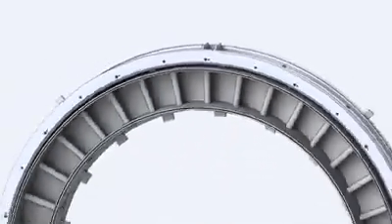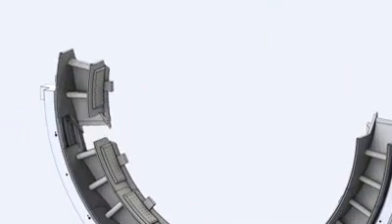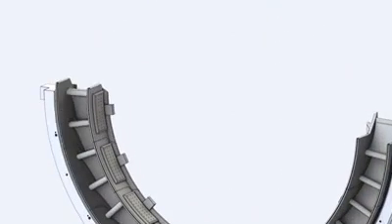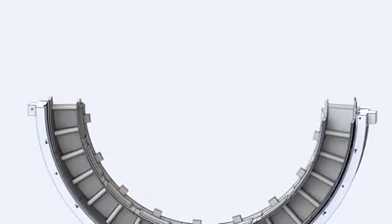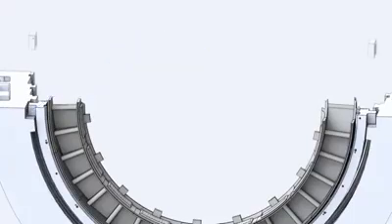The 18 segments are contained on a horizontally split retaining ring. The retaining ring is supported to the lower turbine shell by 2 lugs extruding from the lower retaining ring half and held in place by clamps.